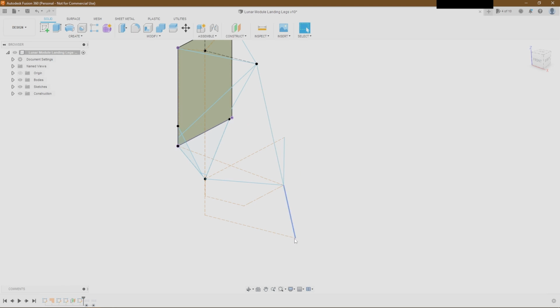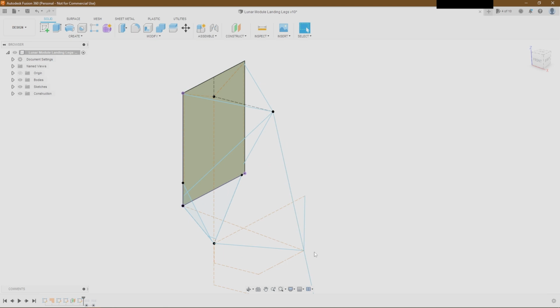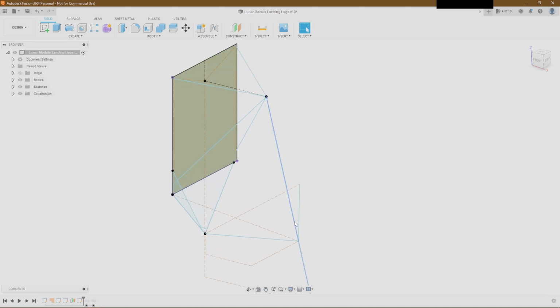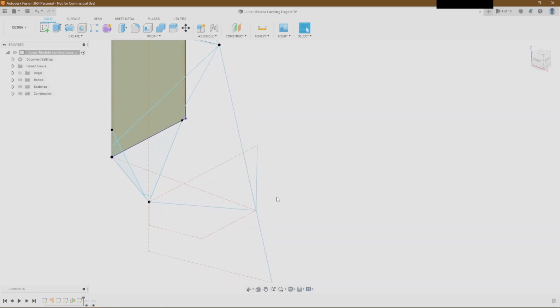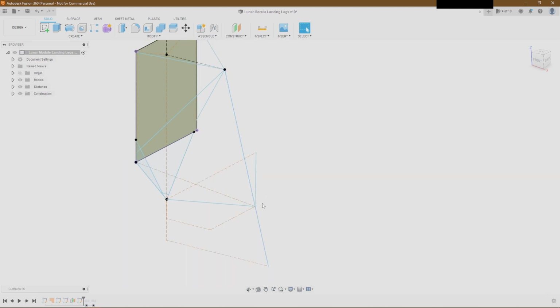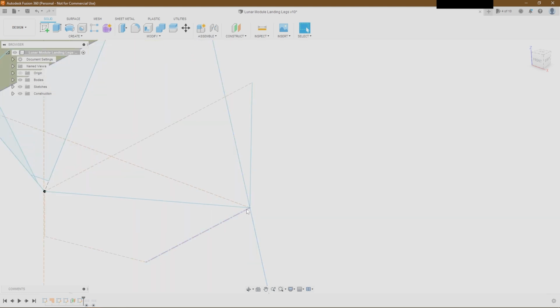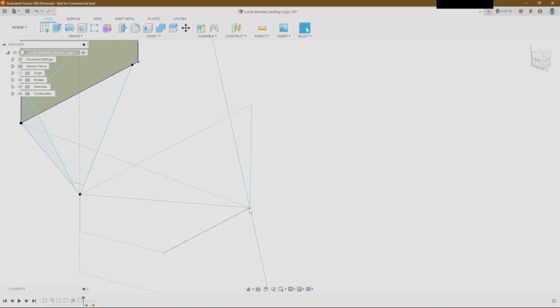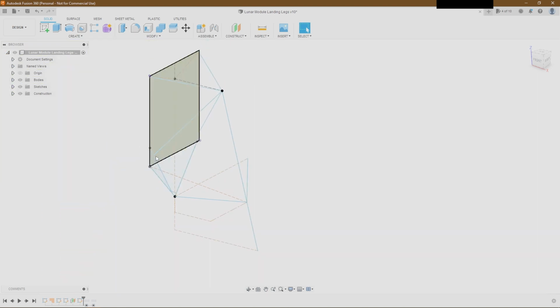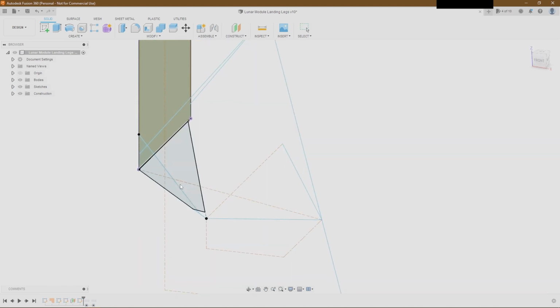You'll note that I did not just make one big line from the top point to the bottom point. This is 2 separate lines. There's a construction line under that is one big line, so I could place the 2 lines on it, but the actual blue geometry is 2 separate lines. There we go. You can see it's highlighted now. So that's very important because we need to essentially ensure that there are nodes on all the struts that come into a singular point. And that'll make sense in a few minutes.